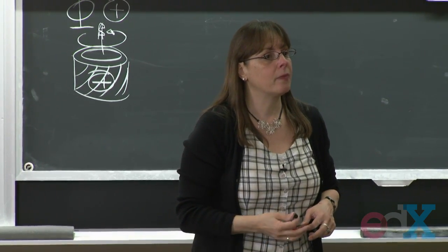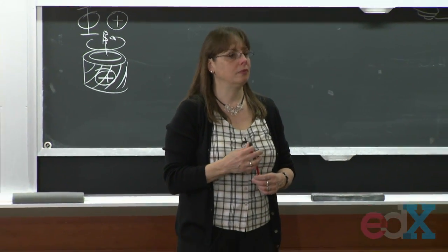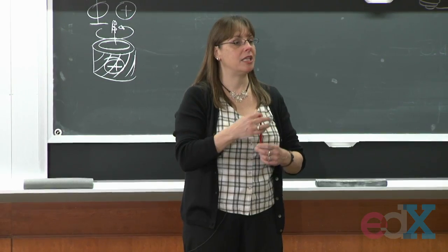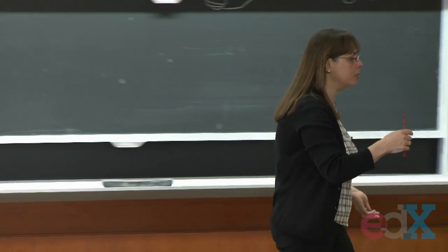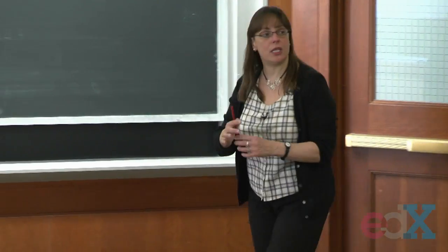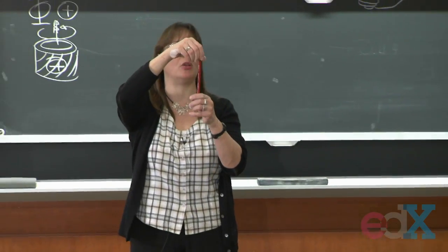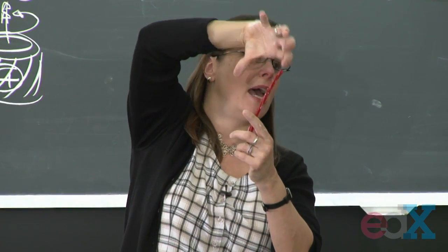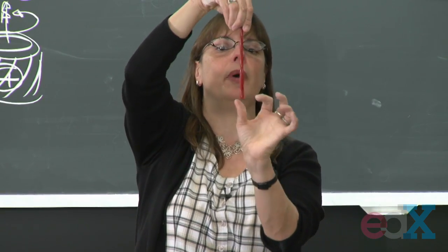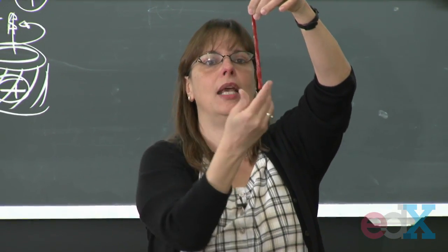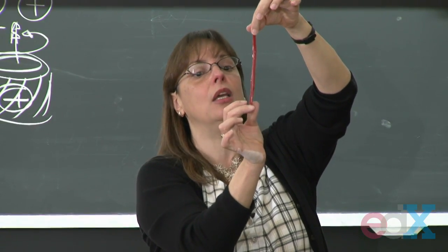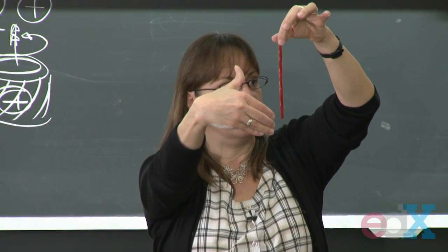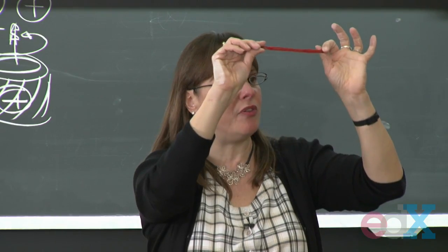So if you hold like the top of the Twizzler and then do that and it reverses it, is that still out? The Twizzler, always, if you look at your thumb, the angle of twist, the twist always goes in. So if I hold the bottom, I untwist and I see what happens. It goes that way, like that. My thumb is in. If I hold the top and I untwist the bottom, like that, and I see the way it goes when it deforms that way, still in. So it's relative to where it's fixed. It's relative to the way it was before it deformed.